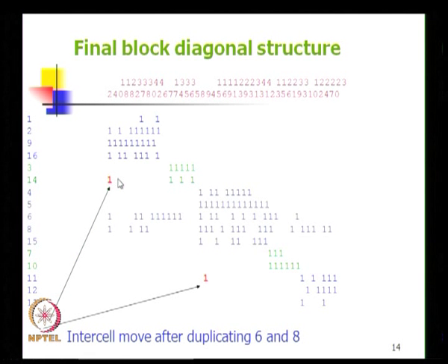The reason I am talking about this is because if we go back to how the machine component incidence matrix was created, we said look at what is happening currently and look at every part that visits machines in the factory, and see what machines each component is visiting. In the present scenario, component number 2 may be visiting 14 for some particular operation. If that operation could be done in machine number 6 or 8 or 16 or 2 or whatever is inside, then automatically this can be eliminated.